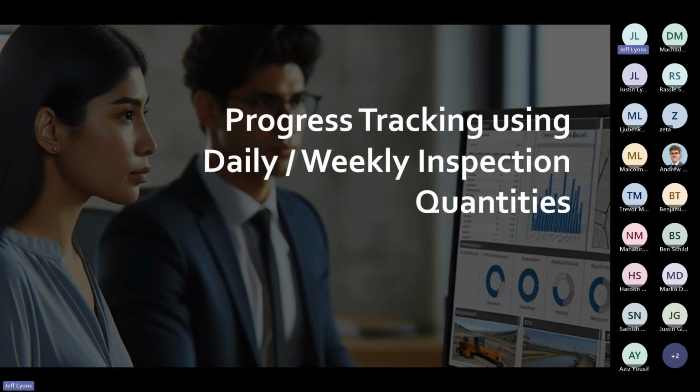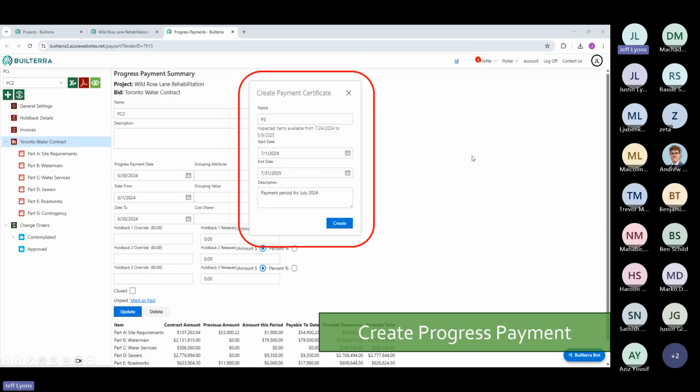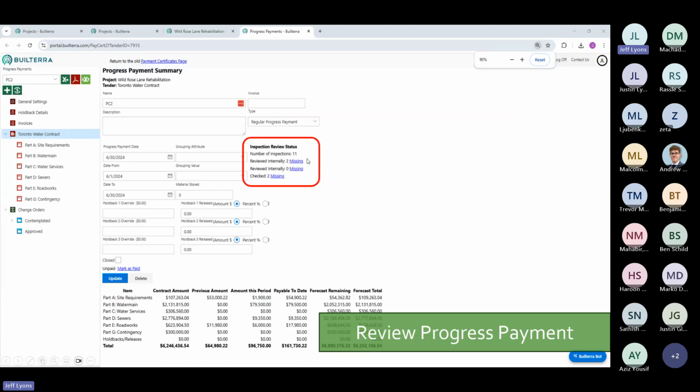Tracking the progress, we take a step backwards and look at the site visit reporting with access to quantities. You can basically build a quantities tracking system. Remember when we awarded the bid, the progress payment system became active, and then essentially we can go ahead and create a pay app or a payment certificate by specifying dates. Within those dates, it compiles all of the inspections that we previously did. So all of those quantities that we collected in the past are now shown here, and it gives us the ability to monitor those.